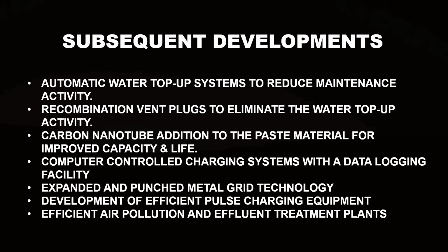Batteries such as those used in material handling equipment or golf carts require frequent topping up with water. These batteries had to be made using high antimony in the alloy because they were used for cycling applications. These batteries are charged and used daily after being discharged regularly. They are charged overnight for use the next day. In these cases, water topping up is required more frequently compared to an automotive or stationary battery.